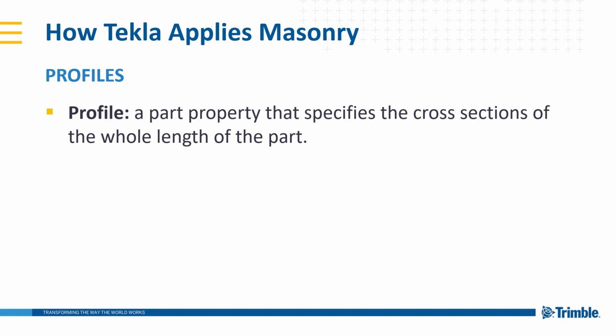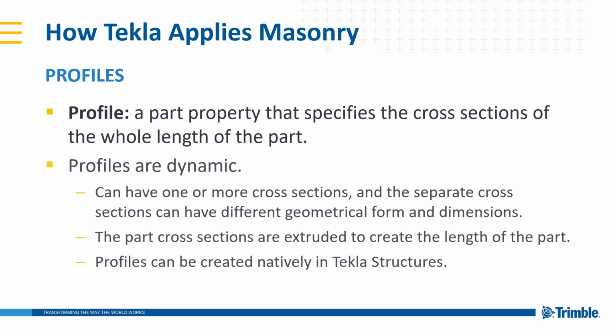Profile is a part property that specifies the cross-section of the whole length of the part. Now, profiles are dynamic and they can have more than one cross-section, and the separate cross-sections can have different geometrical forms and dimensions. The part cross-sections are extruded to create the length of the part or your 3D object, and profiles can be created natively in Tekla Structures.